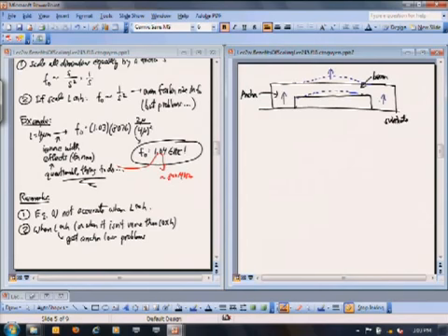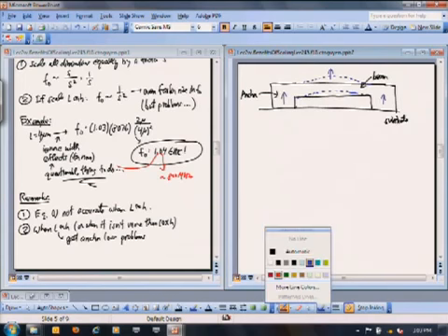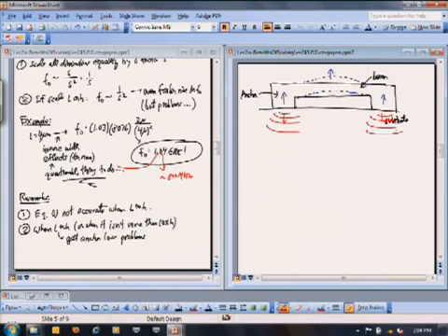And what that's going to do is radiate energy into the substrate. Okay, that is an anchor loss mechanism. And anytime you have loss, right, Q is equal to energy per cycle divided by energy loss per cycle.